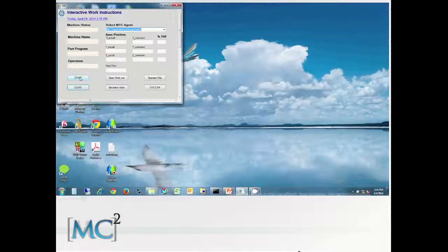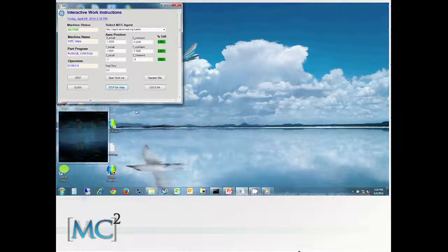So for this first one, we're looking at a simulator from MTConnect.org. And here we have different information. One set of information we're looking at is if there's a drift in the tool path. So we compute the percentage difference, to indicate to the operator that there's some problem with the tool path.